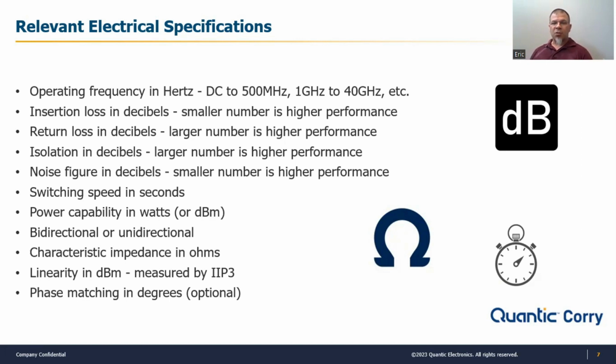And the insertion loss, very important. Can the customer in the application tolerate a great amount of insertion loss, say 10 dB of insertion loss, or is the signal coming in pretty sensitive, pretty small, and any attenuation on it would affect the measurement level?